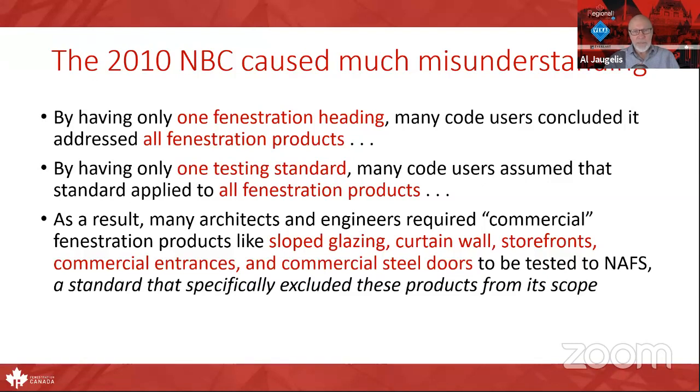As a result, many architects and engineers required these commercial fenestration products like sloped glazing, curtain walls, storefronts, commercial entrances, and commercial steel doors to be tested to NAFS, a standard that specifically excluded these products from its scope.